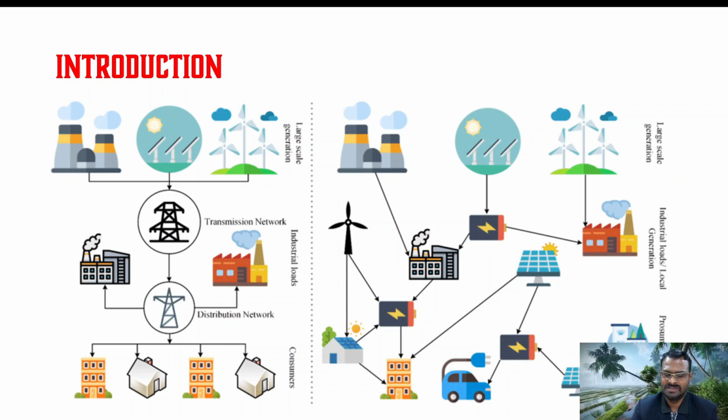In case of deficit, power is taken from the utility grid; in case of surplus, it can be fed back to the grid. By distributing the power production at the required places, the losses in the transmission line can be reduced. The other benefit is that these are renewable sources, so they are available in surplus, and they do not produce much pollution. This is the advantage.